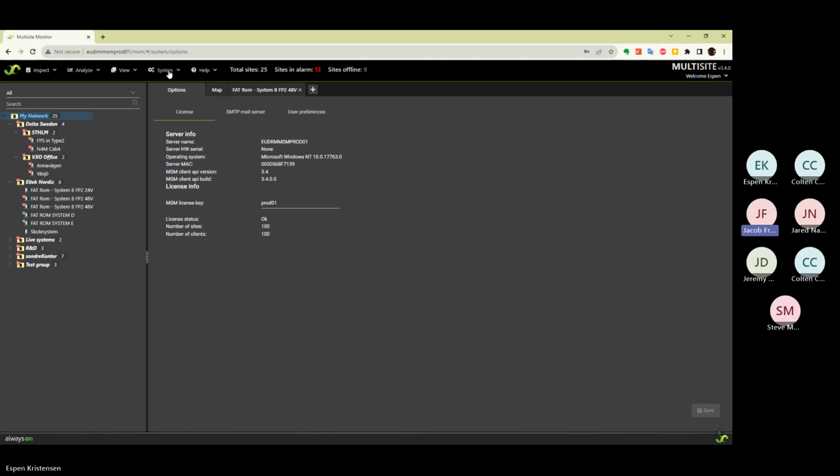Right now on our rectifier controllers, we're using all of the inputs on the input terminal for various types of alarms, door alarms, voltages, all that. Would those still be sent to Multisite? And if they are, would it be as a polled value, checking every minute or so whether that alarm input is alarming, or via SNMP traps?